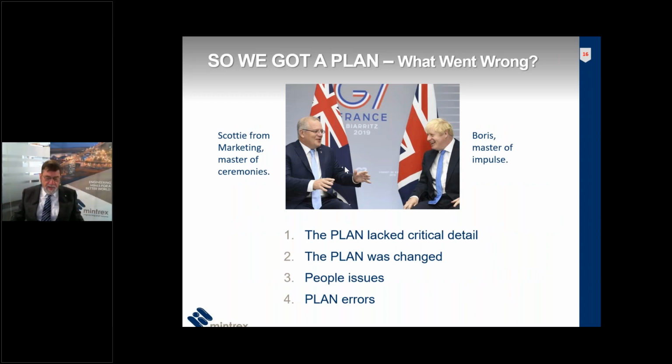So we got a plan, but something went wrong. The plan can lack critical detail: no geotechnical studies, ore samples tested not being representative of the ore that's going to be extracted, no materials handling studies, inadequate survey, with different surveys with different coordinate systems.